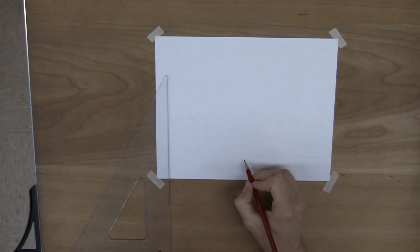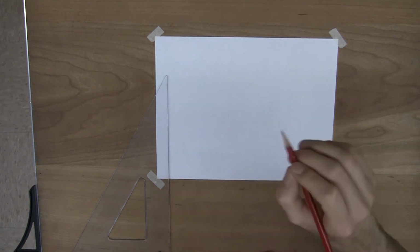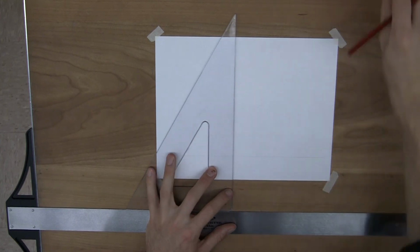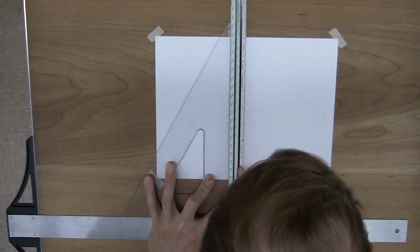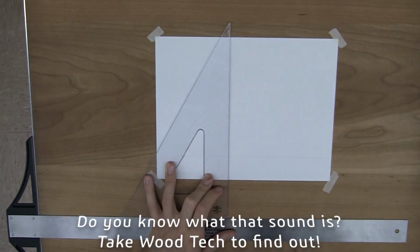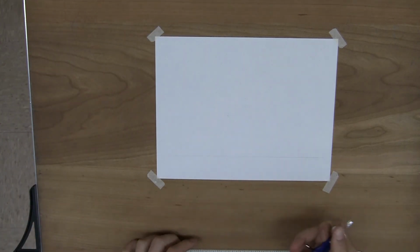To start this drawing, you want to start with the arcs. I know where the center of the drawing space is, I know where the base is. So now where I know the base is, I can measure up 3 1/2 inches, and that's going to be the center of my arcs. There it is. So I'm going to use my compass.